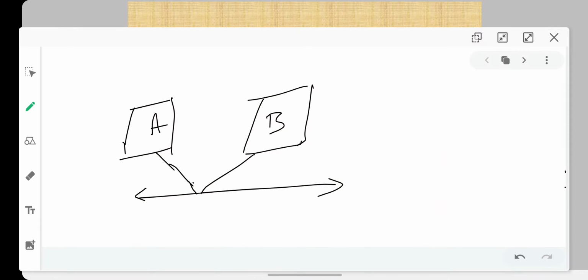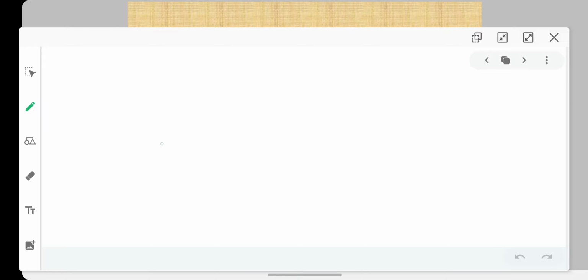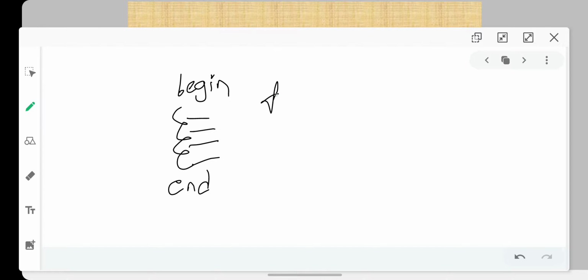For example, you may be aware of begin end blocks. Inside a begin end block everything is sequential. When you write 5 lines of code in your begin end, every line executes sequentially. But in a fork join block, the lines act in parallel. If you have 3 lines of code, all 3 lines will execute in parallel, not sequentially. This is the main difference between begin end and fork join blocks. Keep this concept in mind, because in the next lectures we'll go deeper into fork join and the types of fork join blocks.